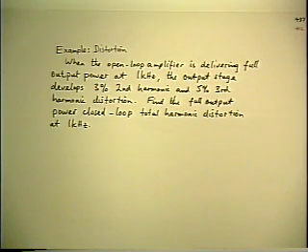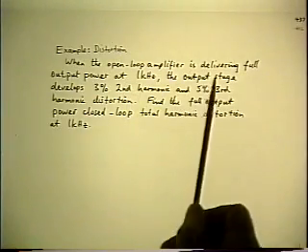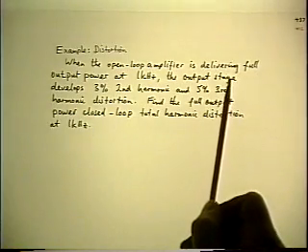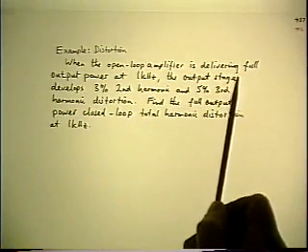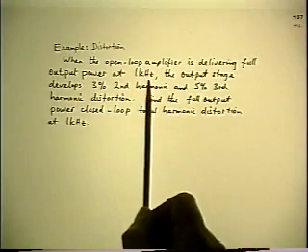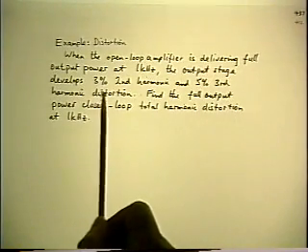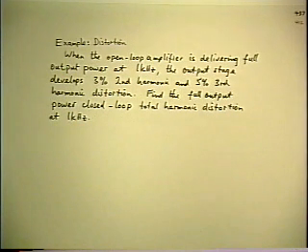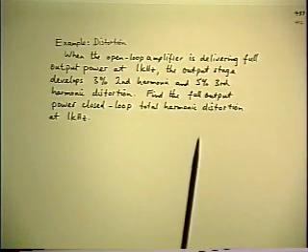That's where most of it comes from, because that's where the signal amplitude is largest, and therefore the nonlinearity of the characteristic is worst, because you're exercising the operating point over essentially the full range. So let's suppose, just to pick a starting point, when you drive this little power amplifier to maximum output at 1 kilohertz, for example, let's suppose that it develops 3% second harmonic and 5% third, which you could find out just by measuring it with a wave analyzer or distortion meter. So that's the reference condition.